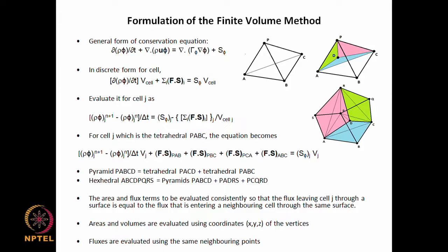All it now requires is how to find these vertices, okay, how to divide the control volume into a small number of bricks of this kind of planar and hexahedral shapes. So that is part of the grid generation. So we are going to look in the next class at some generic approaches for grid generation, as part of which you will be identifying the vertices or the points at which you would like to make the evaluation of the variable values.